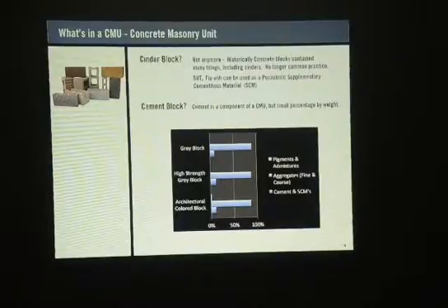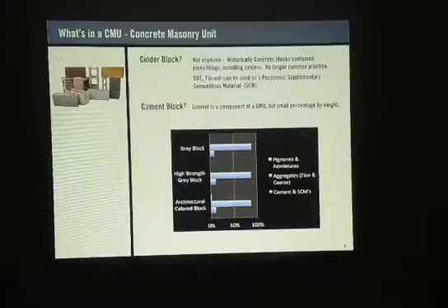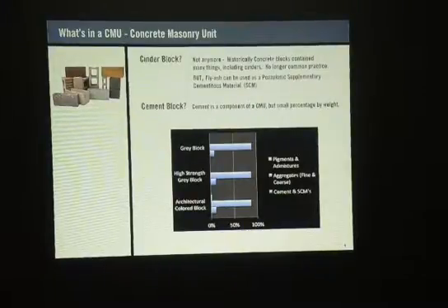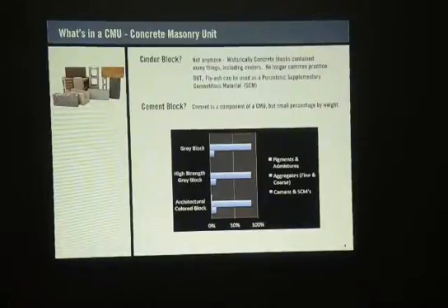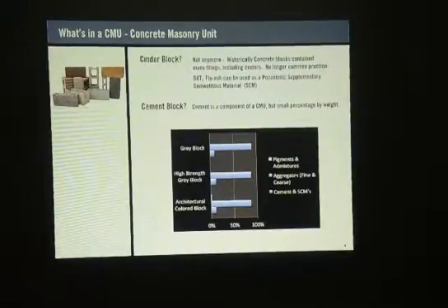So it's not that much more, but you get much more because of the block being fully grouted and also reinforced with steel. So you got a real durable structure, whether you build a wall or a building, if you do have those two factors incorporated into your block. And it doesn't matter if it's lightweight, normal weight, or something in the middle, medium weight.